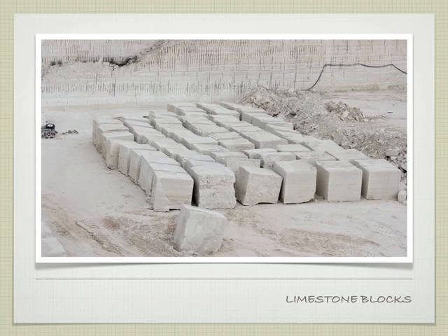They then take that block mechanically to a saw, relatively close on site. It's not a big transportation process. Usually it's a wet bandsaw or something, and that wet bandsaw in granite would slice those thin pieces. It's still a very rough cut. It's not polished by any means. After they slice those rough cuts, they take those slabs, which is what they call them now, flatten them out, and then grind the surface and polish the surface to give you what your countertop would be.